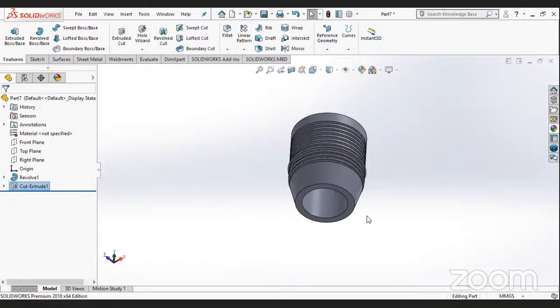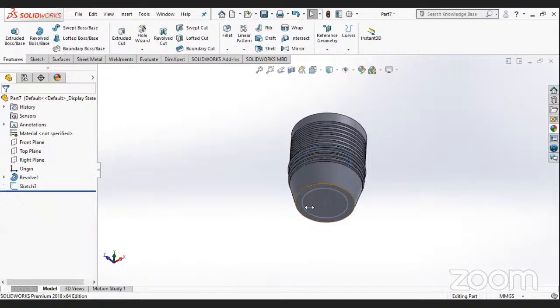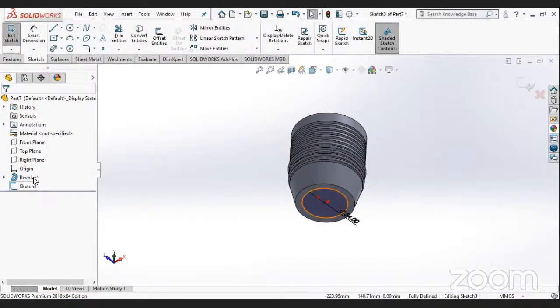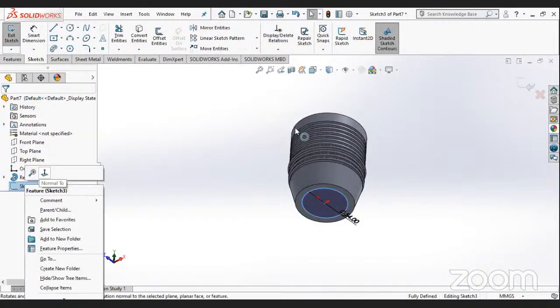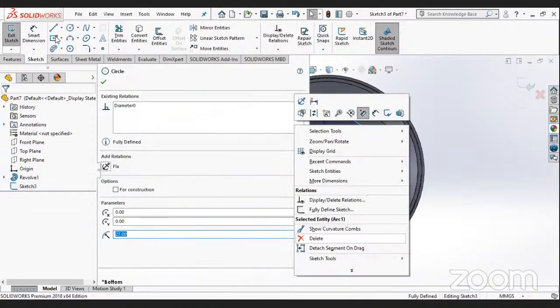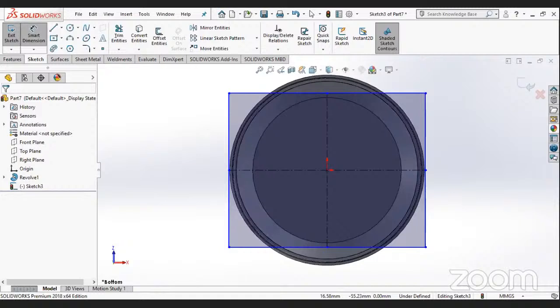Okay, you need the cut in the base as well. So before extrude cutting this circle, we'll quickly make the base and then cut this circle. So I'll just edit this sketch, and instead of this circle, we'll make a base here. Delete the circle. Take a center rectangle. Just make one rectangle and start with the dimension. We'll quickly take the dimension of the base.